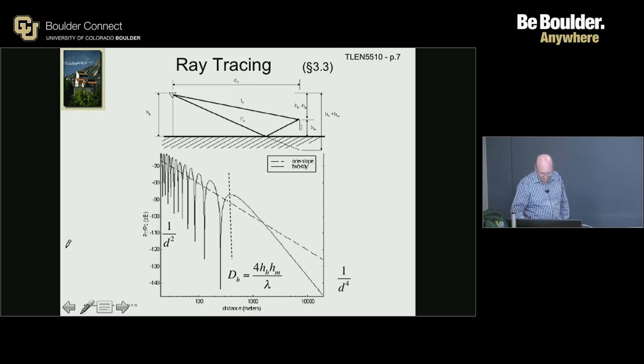And here we've plotted, I'm sure this is no secret, you notice that the x-axis is in logarithmic scale. Therefore, when you plot a 1 over d squared variation on the logarithmic scale, you see a slope of n equals, I heard somebody say 20. Yeah, I mean the slope is -2, or minus 20 decibel per decade.